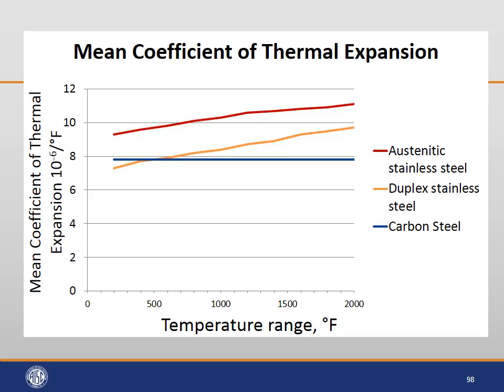If the surface area of the aluminum will be much larger, which is implied possibly by the roof being aluminum, then you may not have an issue with galvanic corrosion. It's all the relative surface areas that are important. I'm assuming a canopy is small, the roof is large in terms of surface area.